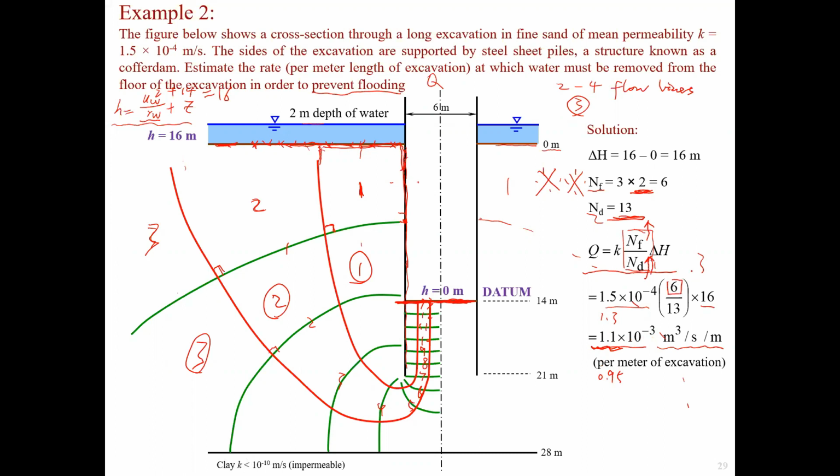Because this value from your flow net will be 6, and then ND maybe 15. So the ratio may be different, but only a slight difference. As long as it is within the allowable range, that ought to be fine, because we allow some human error involved in the hand calculation. That's unavoidable.